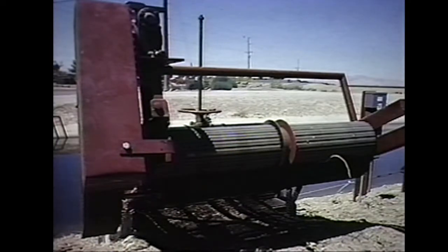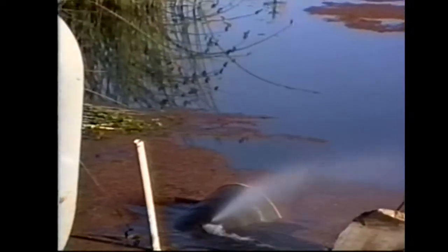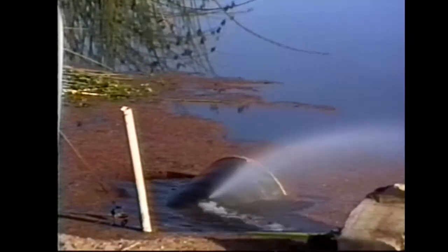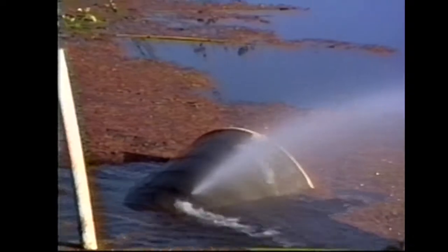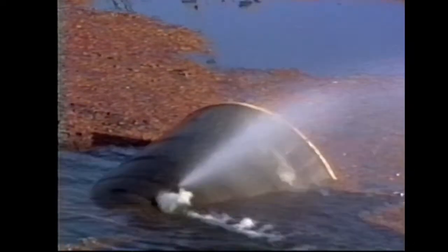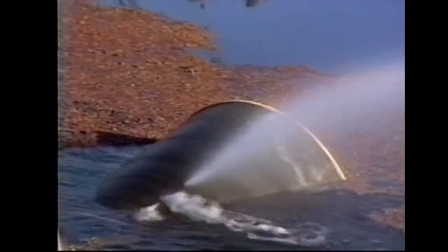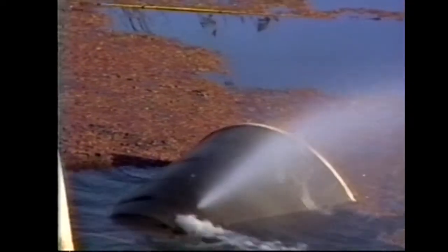These rotating belts are almost always fabricated locally in a machine shop. They are powered by AC, DC, or hydraulic motors. Another pre-screening device has a specially designed screen cylinder around a pump suction pipe. In this design, the screen itself rotates. Part of the pump discharge water is used for spray water and to rotate the screen.